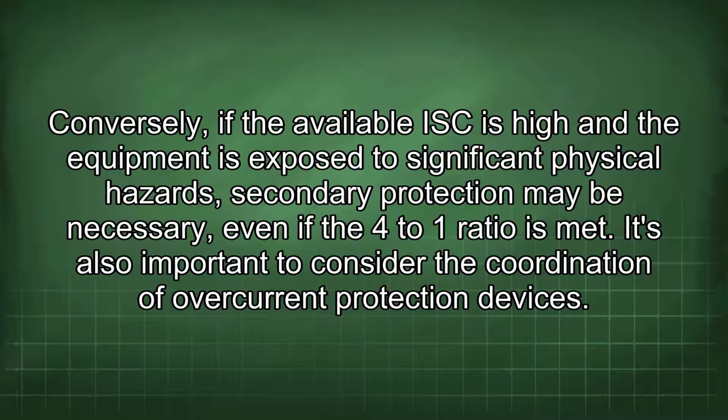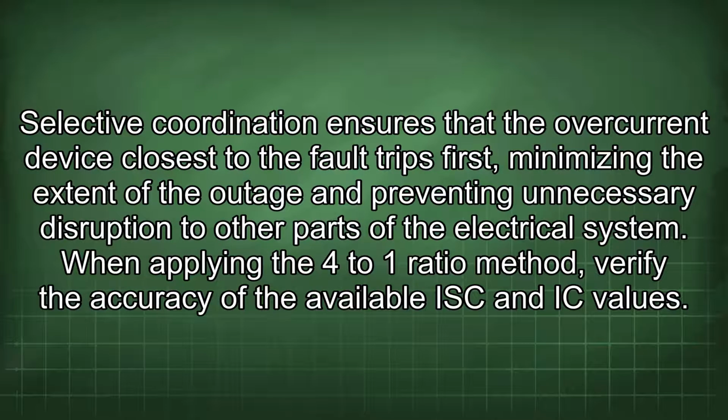It's also important to consider the coordination of overcurrent protection devices. Selective coordination ensures that the overcurrent device closest to the fault trips first, minimizing the extent of the outage and preventing unnecessary disruption to other parts of the electrical system.